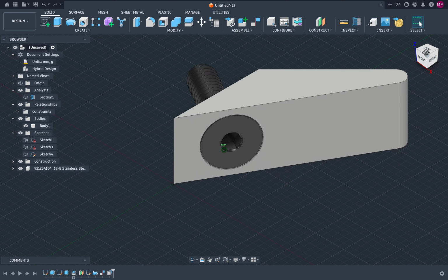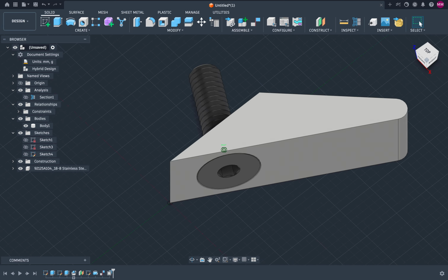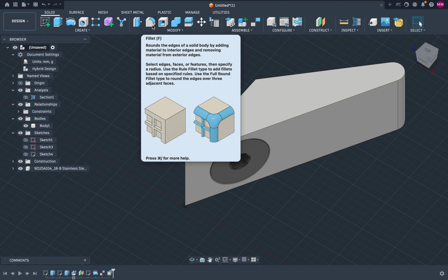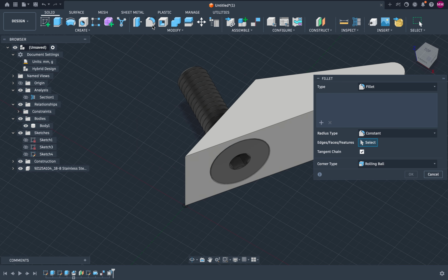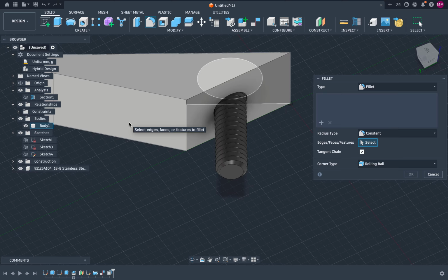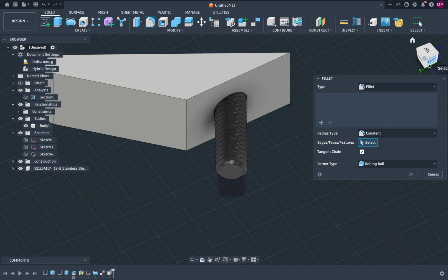But as you can see, it doesn't look that finished, right? We still have all of those sharp corners that 3D printers will not be able to handle. So let's switch our brains from design to manufacturing. How can we make this thing easier to manufacture? Let's imagine it will be printed on this flat side that we have over there. Oh wait, here it is. Therefore, the only support that we'll probably need is on this side, and we will probably only need to sand it a bit, if we need to sand it at all.